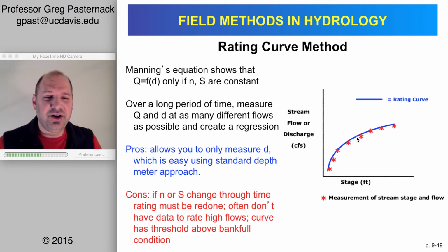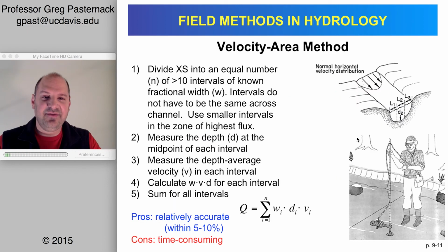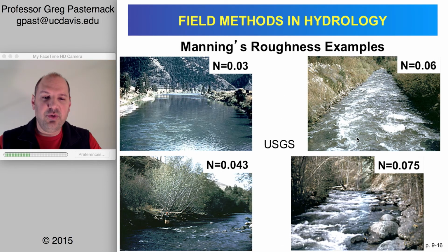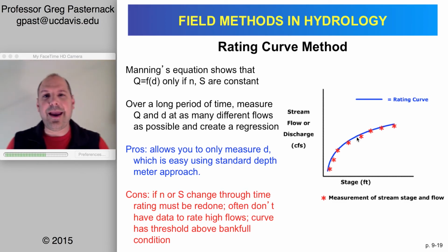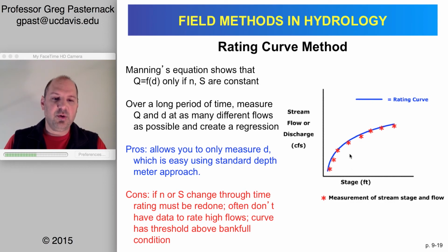And so this is what makes discharge hard, and I'm not sure I've conveyed this as logically as I could have, but when you want to get discharge measurement, for hydrology, we often want to get the hydrograph through time, not just an instantaneous discharge measurement. All these methods here were about getting an instantaneous measurement, velocity area, ADCP, weirs and stuff. But if you want to get it through time, you got to go through a rating curve. And whether the rating curve is your weir equation, your flume equation, or Manning's equation, or a best fit empirical function to the stage discharge observations, then this gives what's called the rating curve method. So in the field, we continuously record stage, usually on a 15-minute interval, and we compute discharge from that. Now, let's say you have a big storm that comes through.